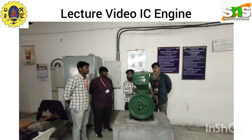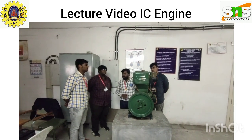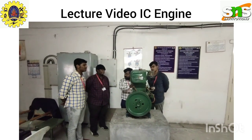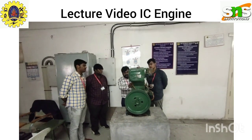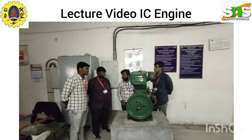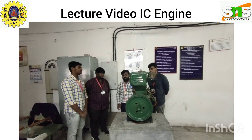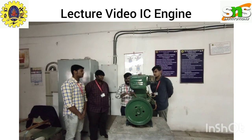This is also made up of cast iron and aluminum. Then the piston is the device which transmits the energy to the connecting rod. The small end of the connecting rod is connected with the piston. The big end of the connecting rod is connected with the crankshaft. This connecting rod converts the reciprocating motion of the piston into the rotary motion of the crankshaft. This is also made up of aluminum, nickel alloys, cast iron, some alloys.